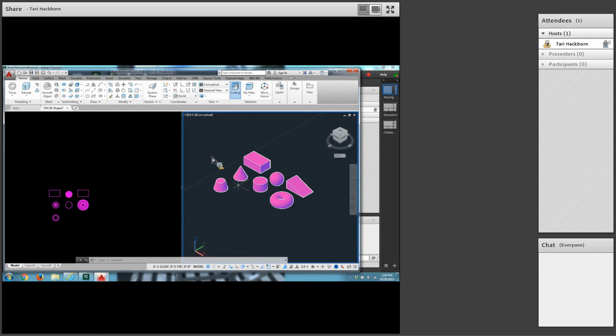Okay, so now we're going to draw an extruded rectangle on page 54, it looks like. Nope, halfway down page 53. Sorry, I skipped a paragraph here. Halfway down page 53, you're going to draw an extruded polygon. Where are you, polygon? Right here. Enter 6 for the number of sides. Center point will be 2.75, comma 5, or 2 3/4, comma 5.